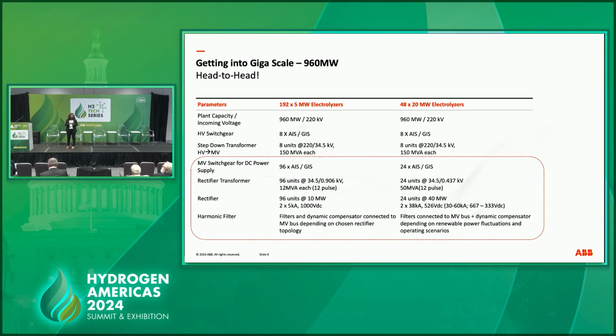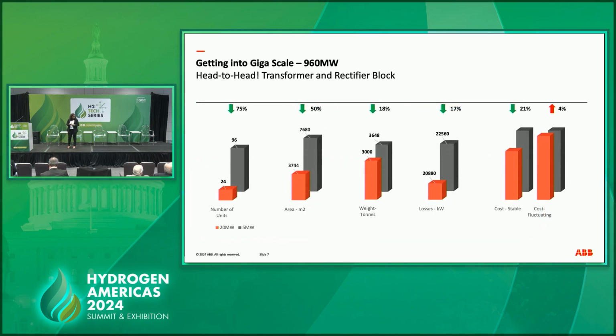If we have a strong grid, a hydro grid, a nuclear grid, something very stable, the filter issue is not going to be big. All the chemical plants out there using thyristor rectifiers have standard static filters, and we've delivered multiple such projects around the world. It's a market standard.